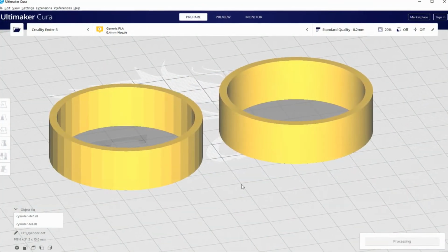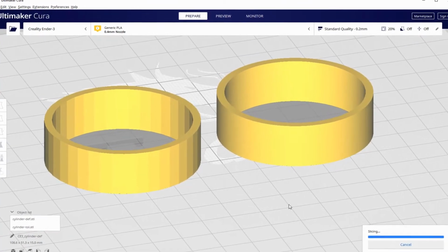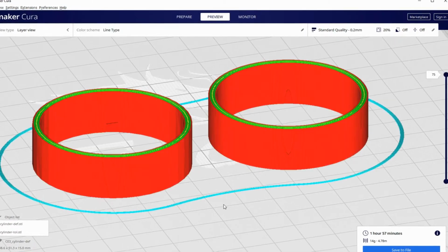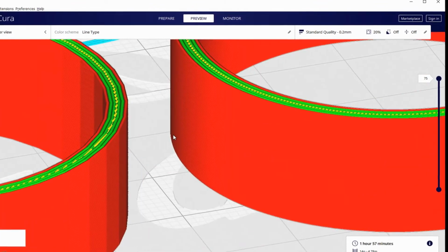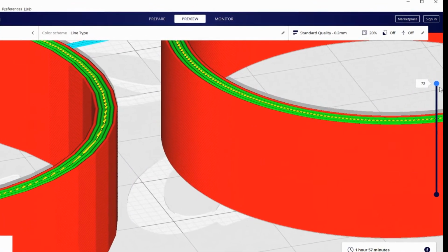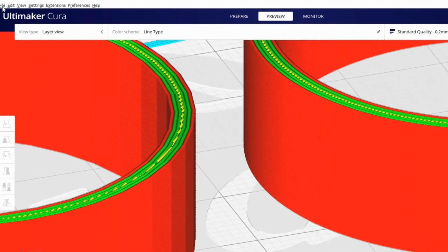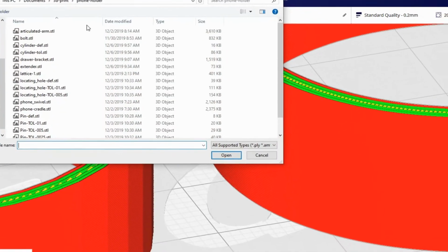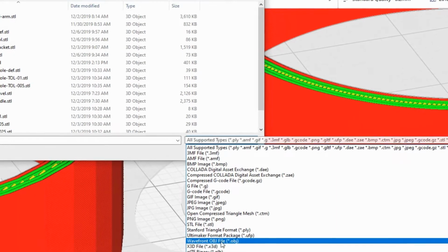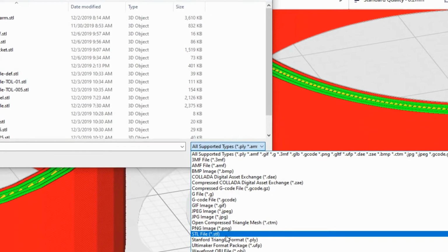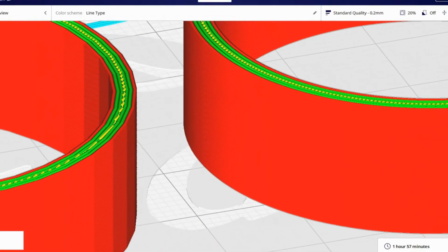Although an old format, faceted STL files are still commonly used for rapid prototyping applications. I export STL files from NX and use Cura software as my slicing program because it works with my own 3D printer. Between NX and Cura, I can also use 3MF files and OBJ files, but these don't provide any additional capability for my applications. They also use the same tolerance values.